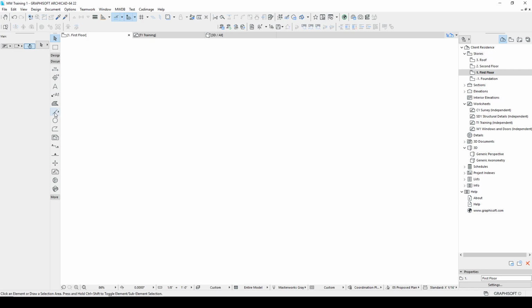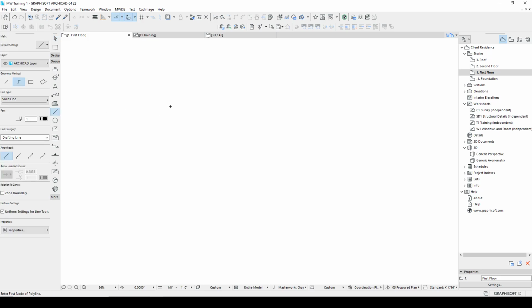get started. So obviously I can use the button over here, and that's my line tool, or as you know how important it is to me, we're going to use the L for line. And once we do that, this is CAD style. There is a setting somewhere in the menus that it's Mac style, where it's a click, drag, and release. We don't want to do that. We want to do 2 clicks, and the system is set up as the default, which is CAD style. Make sure that you're set up in CAD style. So if it's acting a little funny, go check that out.